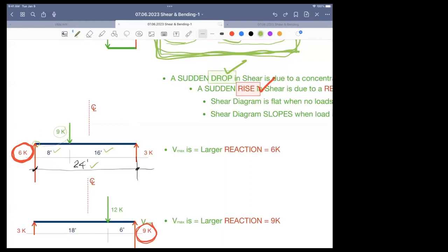We don't have time on the ARE for any of this. So we're going to do a quick shortcut, hopefully, that'll clear the air and get us going quicker. Okay. The 9 kip will break down in the proportion of 8 to the total. That's one reaction. And the other reaction is 16 to the total.